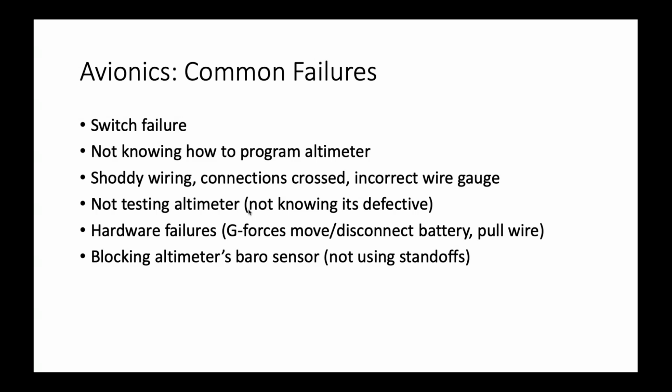or there's something tied to a weight or something shifts in there, the G-force upon launch can sometimes mess that up. The only way you'd know that is during launch your parachutes don't deploy or your electronics don't work, and you really only find that out afterwards. So we have to do everything we can before launch to prepare for it and mitigate it beforehand.